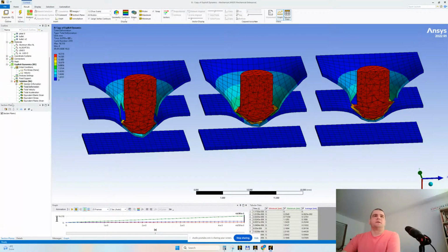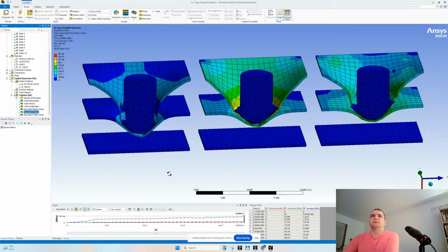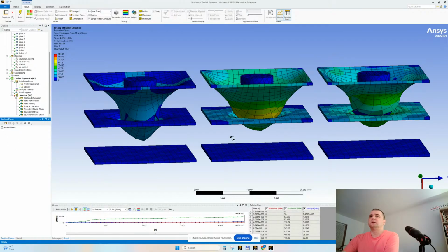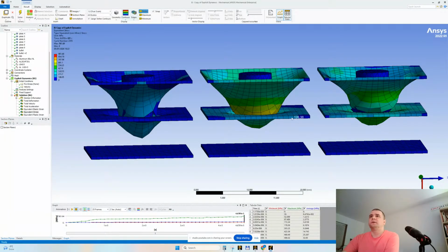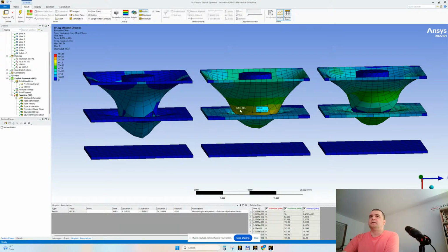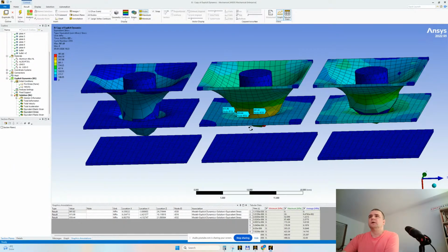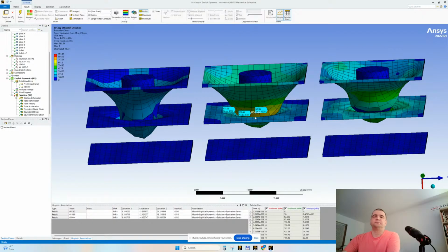You may be asking yourself, hey Claudio, why do we need to have breakage here on this plate? Why is it mandatory? Because we are going to take a look at the stress. Look here. It has the highest stress. Yes, let's scope a little. Probe. Yeah, and the aluminum thin plate should be broken because we exceeded the ultimate tensile strength.